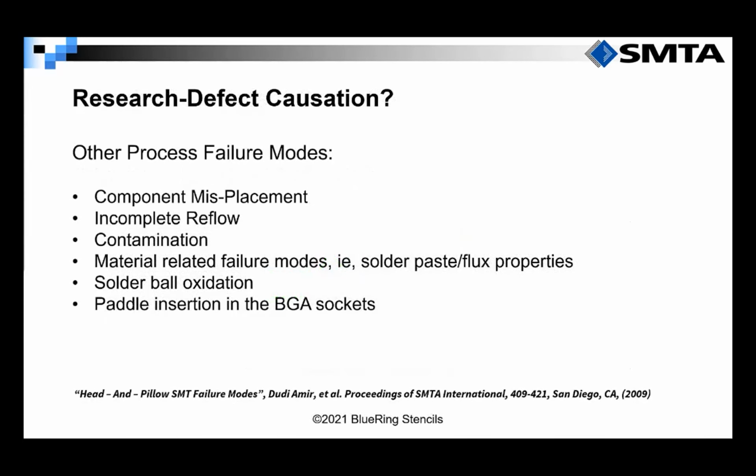I want to stress here that just changing the stencil design is not a magic bullet to eliminate all head and pillow defects. This challenge is very complex and there can be many different contributors. In fact, many times, minor tweaks in 2 or more of these variables are required to eliminate head and pillow defects. So I wouldn't be doing my job if I didn't briefly discuss other areas that should be addressed when addressing head and pillow. These include component misplacement, which can be a key contributor. The reflow profile is also critical when addressing this defect. And we see a lot of customers focusing on both stencil design and reflow profile when addressing this issue.